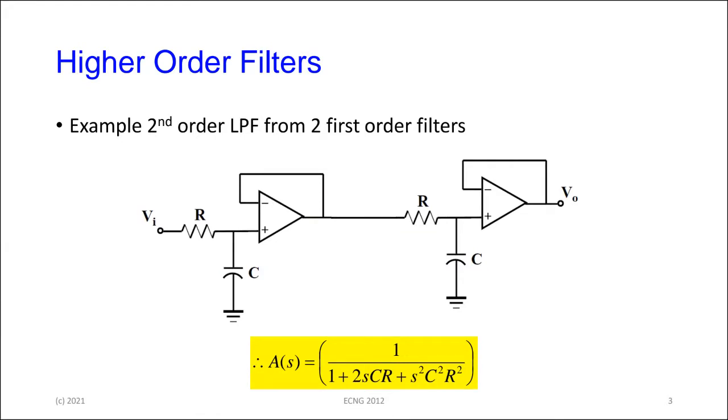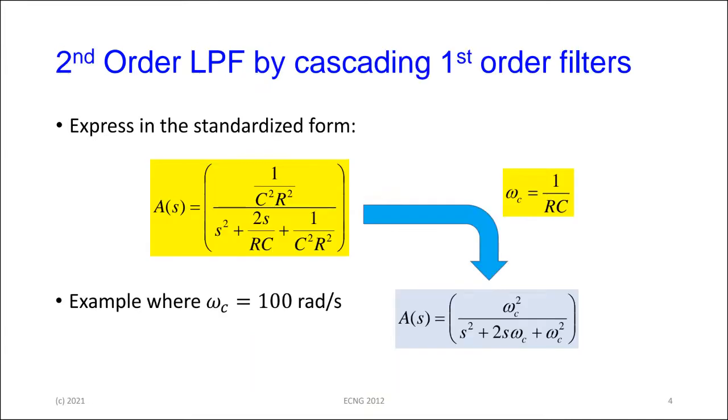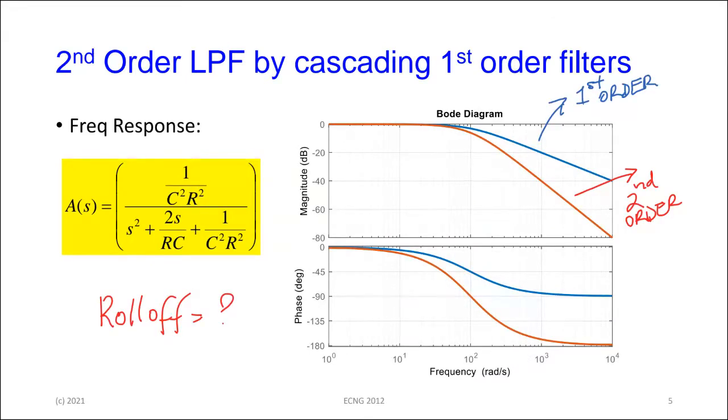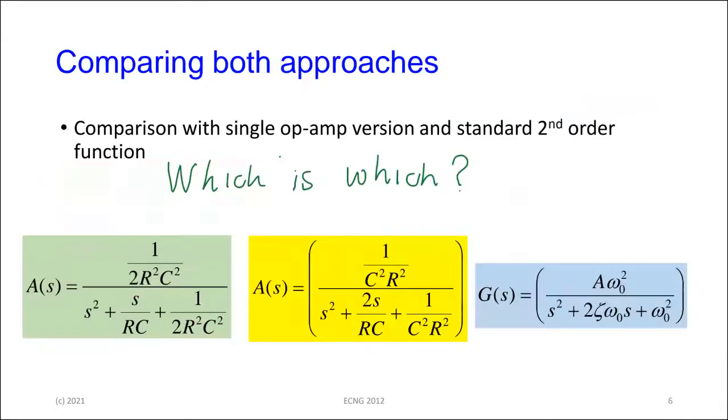And then you just assemble the circuit here. Yesterday, to create the first and the second order function, remember, if it's a low pass filter, the capacitors are equal, but one resistor is twice the value of the other one. So it gets a little bit more complex at that point. Right? So you have different value resistors in that case. Yeah?